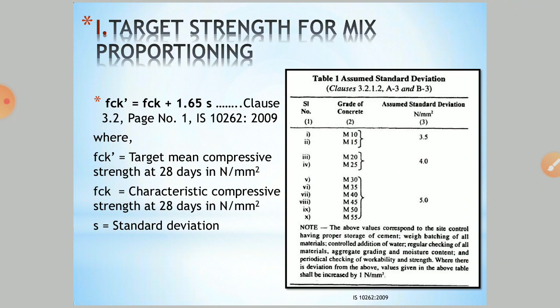First step, target strength for mix proportioning. The formula is given in clause 3.2, page number 1, IS 10262 2009.